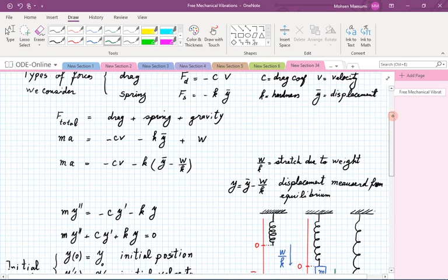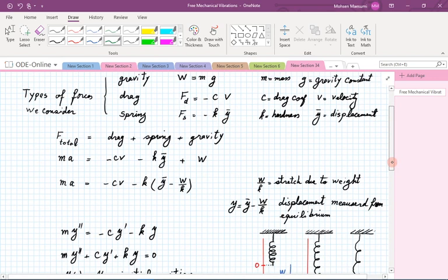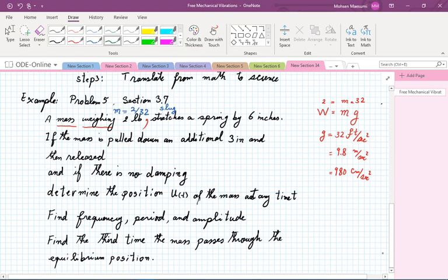So we go back to Hooke's law. Hooke's law is this: a force is going to stretch a spring proportional to the force that you are applying to it. The constant of proportionality is the hardness of the spring. So we are going to go ahead and extract the hardness from here. When we are doing that, we don't need to put the signs in that section of the formula. We're just trying to catch the k. So here we say the force, which was 2 pounds, is going to cause a stretch of 6 inches. What is 6 inches? 6 inches is half a foot.